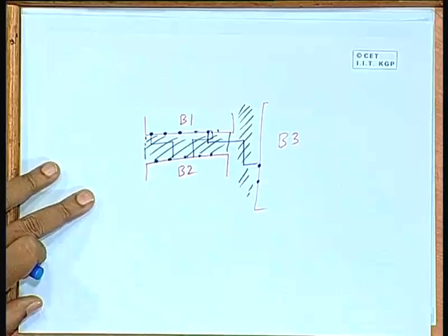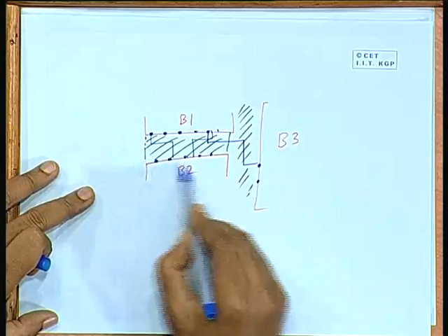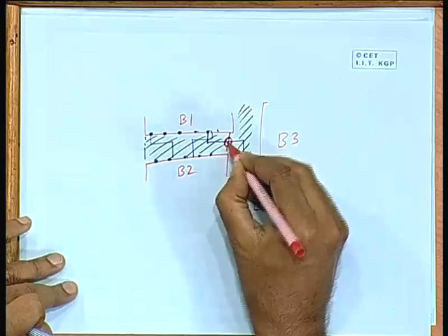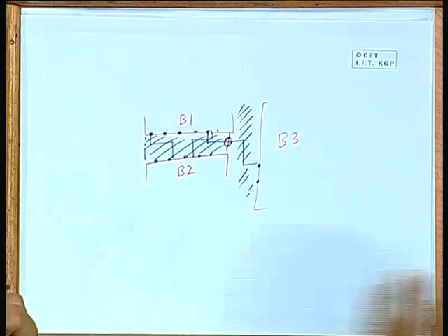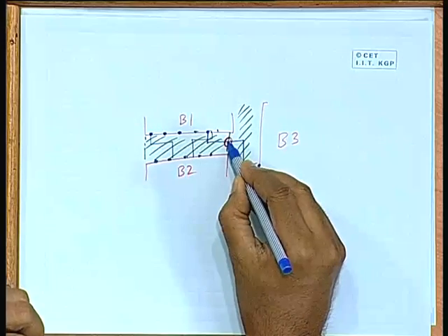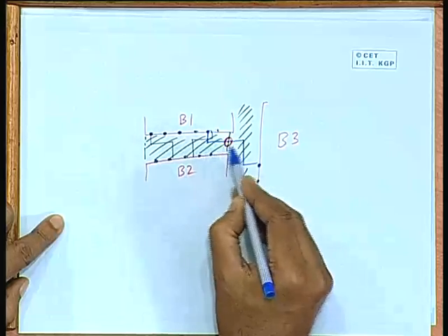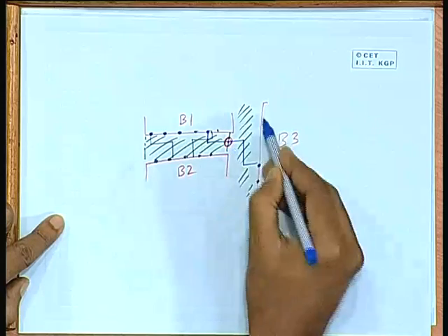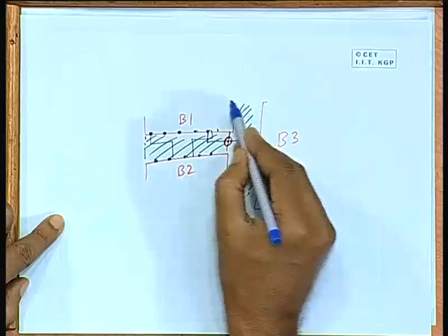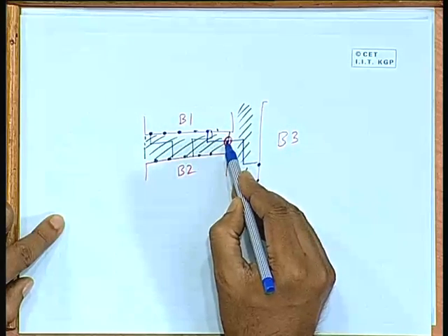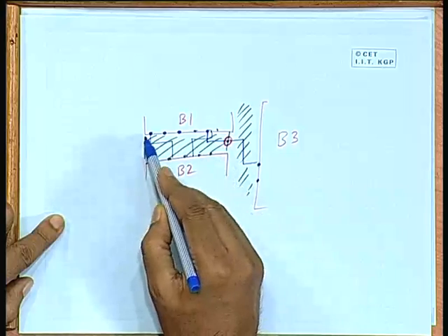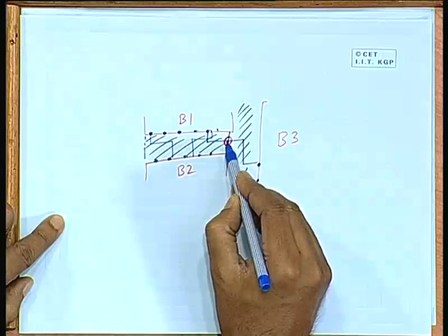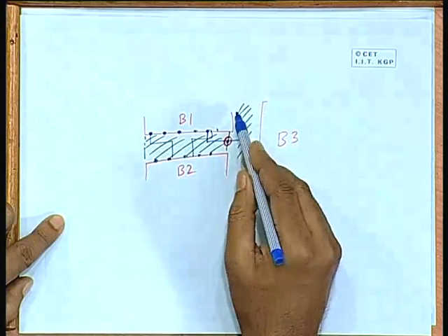Now, the point to note is that when we are starting the problem of routing this particular region, you look at this point where this wire is crossing the boundary. The exact location of this point is not fixed. This wire we can lay out on the first track, on the second track, on the third track. So, initially this terminal is called a floating terminal with respect to the second region. For the second region the location of this terminal is not fixed, but once the routing of this is completed, the location of this point becomes fixed. So, now this becomes more like a fixed terminal with respect to this region.